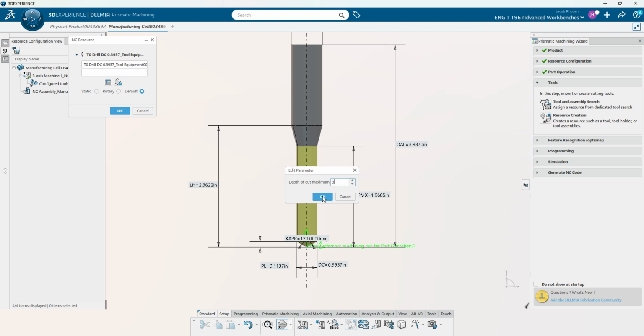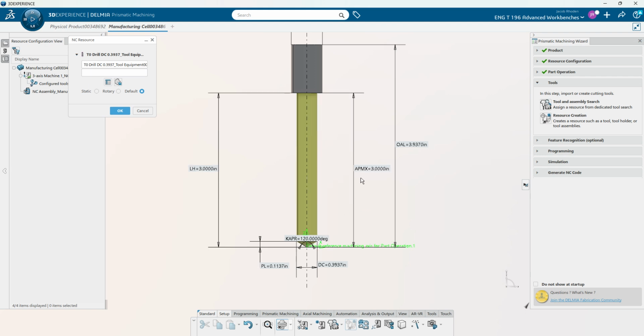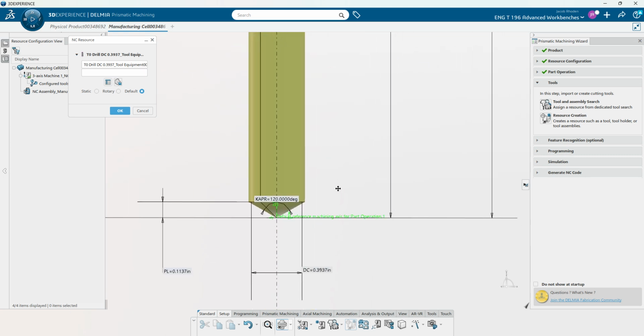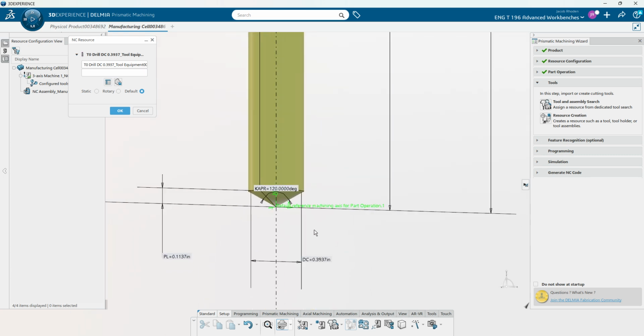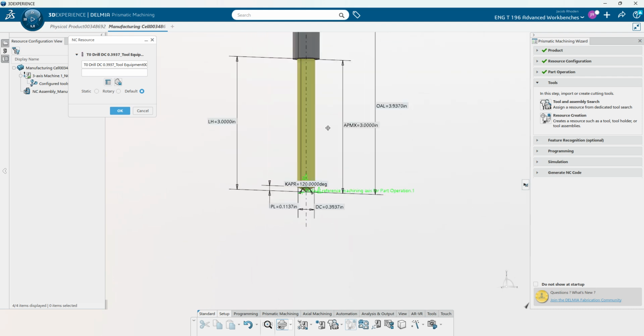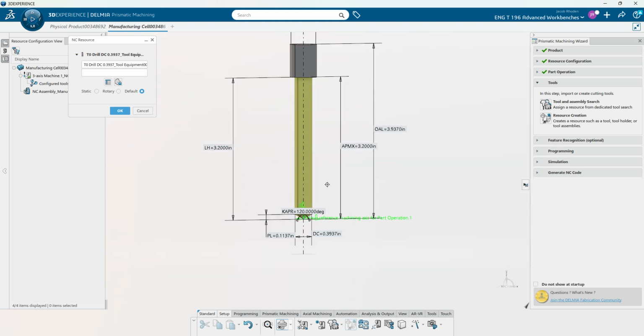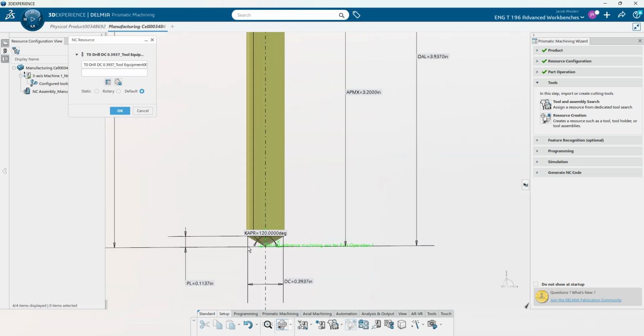Now if we set this to 3 inches, you would think, okay, now we have a 3-inch tool that can go through a 3-inch part. But you'd be incorrect, because this can only go up to this face right here, and as we can see, the tip is going to reach that 3 inches. So that's not going to fully go all the way through and clear that hole up. So we'll add a little bit extra, we'll make this 3.2, and then you can see this will go all the way through the part itself and have enough room to clear that hole off.